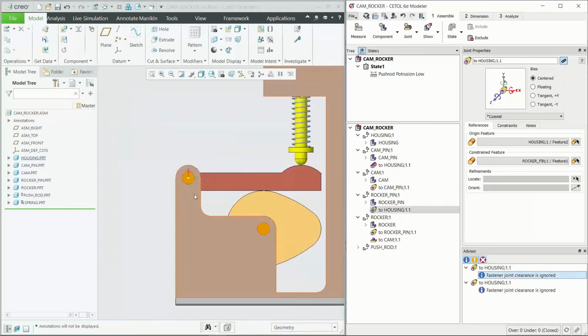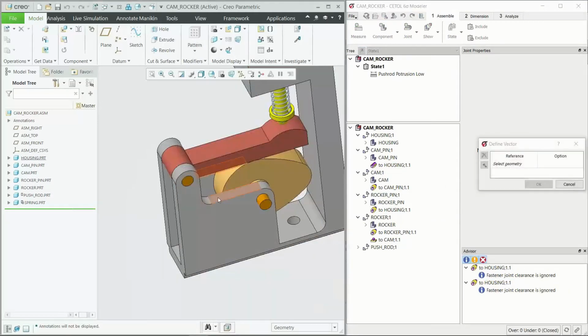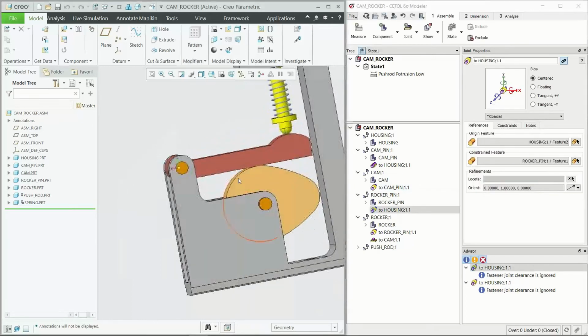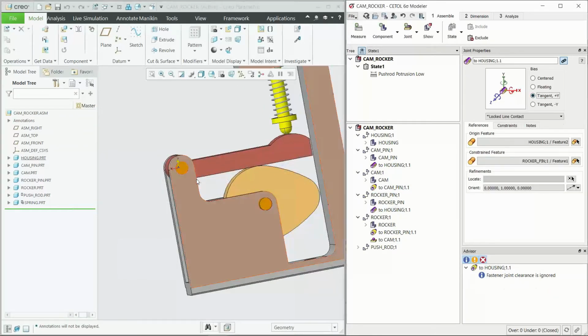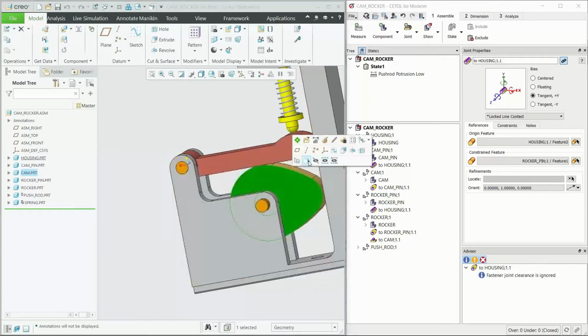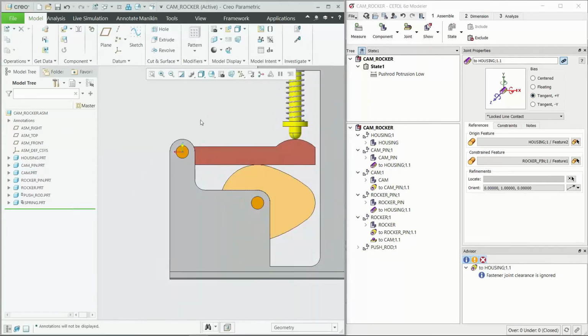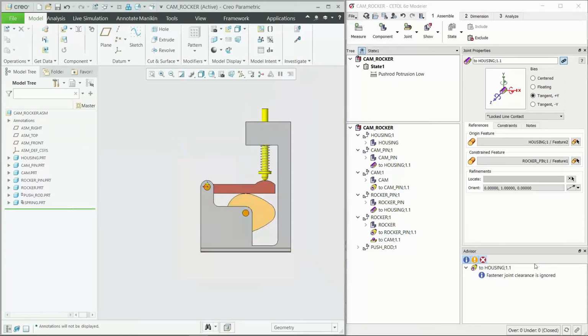The same here. If I would push down here due to the lever effect here, in this case, I would push upwards for this hole. So let's fix that. And that's what's usually happening with your assembly. You will always have some kind of forces acting on the system, be it gravity or some kind of spring forces. So we'll have contact here at the bottom, here at the top.